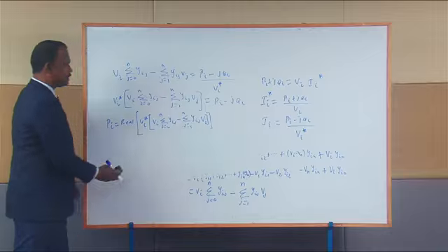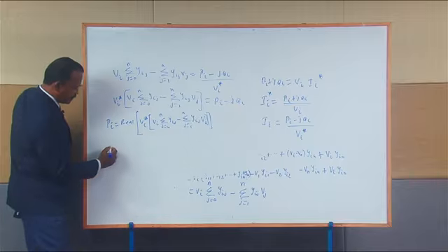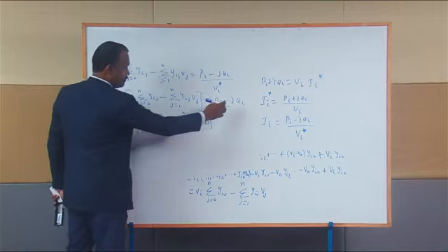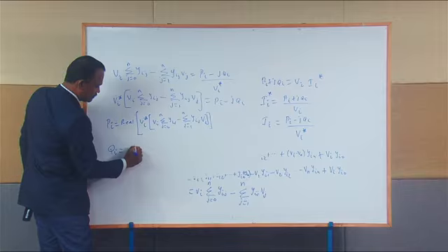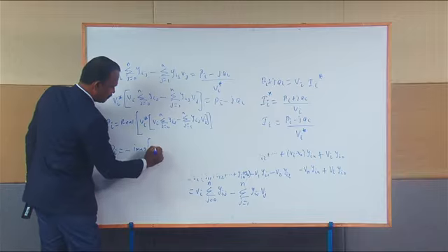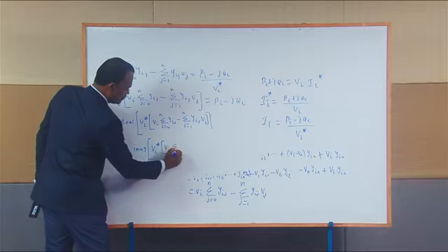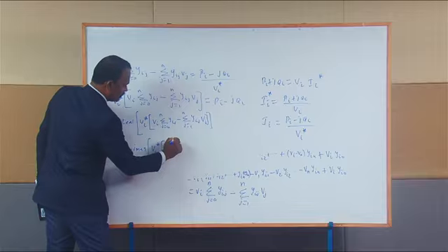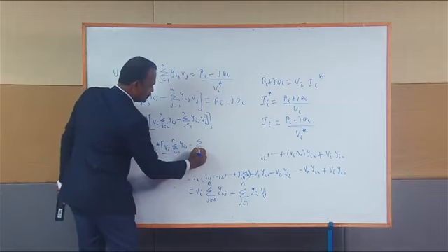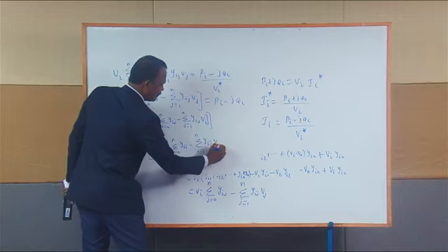Similarly, if you compare the imaginary components of left hand side and right hand side, I can write Qi is equal to minus, because we have minus here, so minus imaginary of, you take this term Vi conjugate Vi sigma j running from 0 to n Yij minus sigma j equal to 1 to n Yij into Vj.